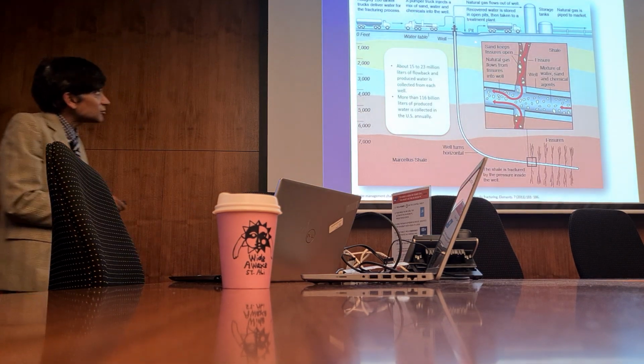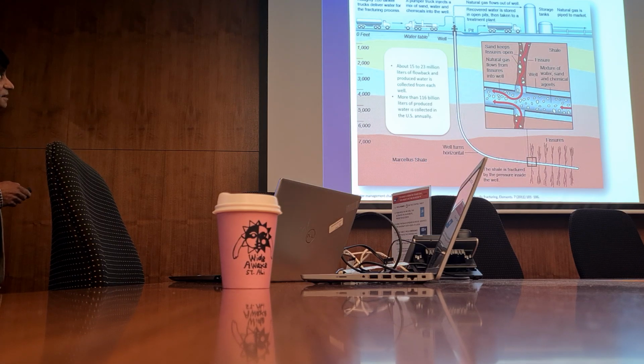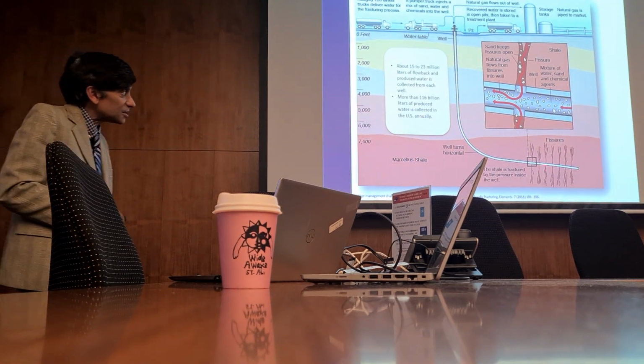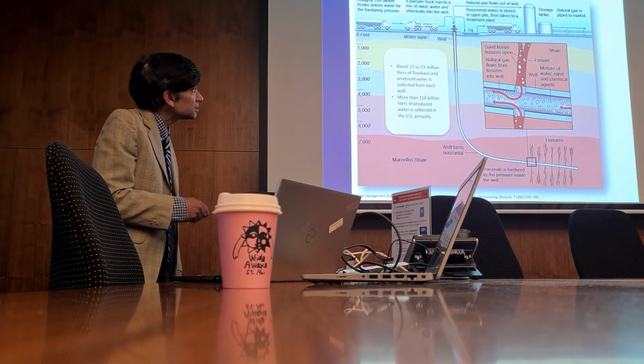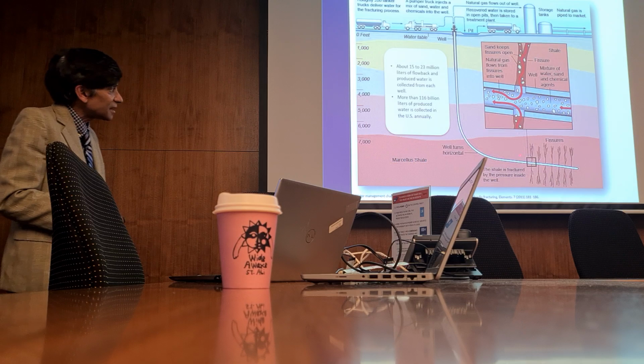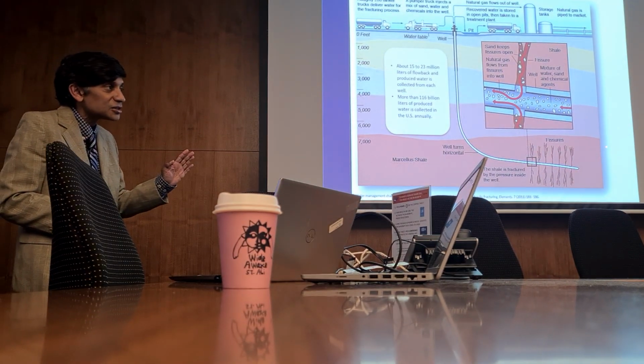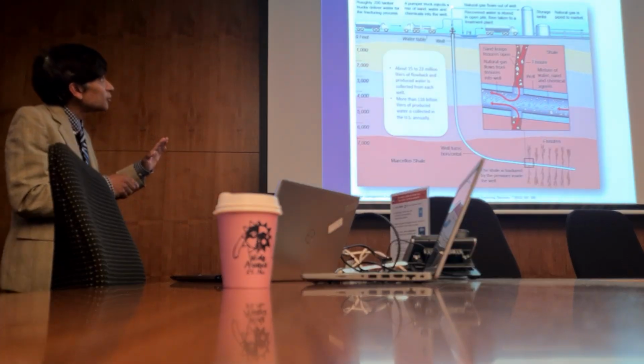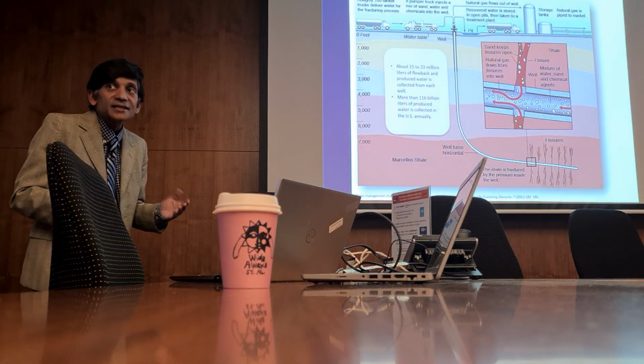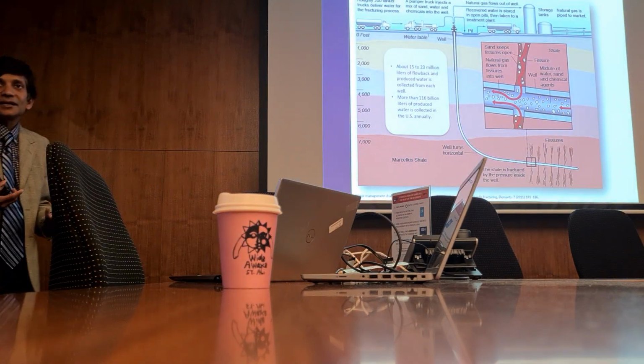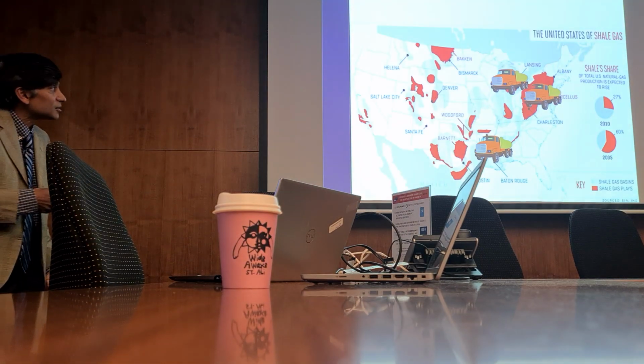So the hydraulic fracturing operation basically is taking a drill and going to the Earth's crust until you reach this tight rock formation, and then turning it and going horizontally for up to 3 kilometers, and then you send water at high pressure, which basically fractures this rock formation. I mean, it fractures it, it causes fissures. You have proppant, which is basically sand particles that go and get stuck in these fissures. When you release the pressure, you get the flowback water, you get your oil or gas, but the rock is more permeable now, so you're more able to easily recover the oil and gas.